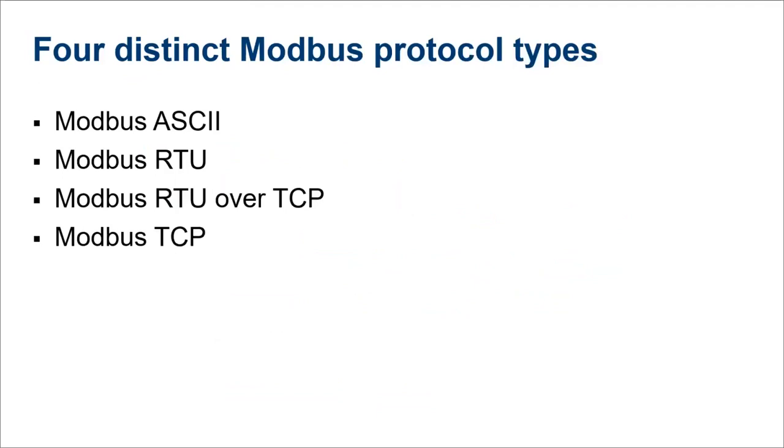So it was largely inefficient compared to binary transfer. Modbus RTU just sends the native hex characters, your 4-bit values for 0 through F, and it provides all the information over a serial connection. So this is one of the most common.